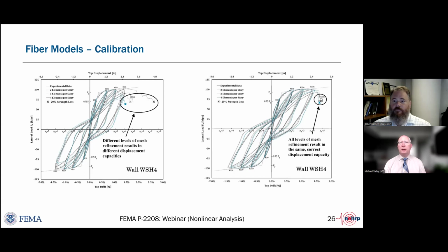On to critical and ordinary actions. The question: why is the load factor for ordinary force-controlled behavior not between the values used for critical and non-critical? That was a judgment decision of the standards committee. There was no statistical basis for that. In fact, the only statistical basis was for the critical load factor, which was how much you had to separate the mean demand from the lower bound capacity to achieve a 90% reliability.